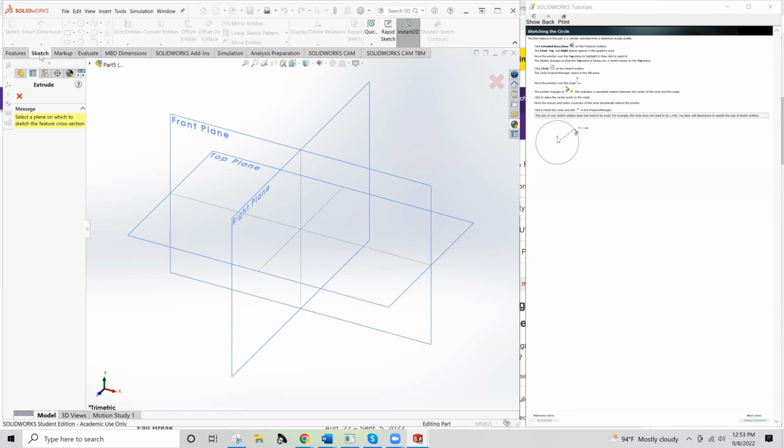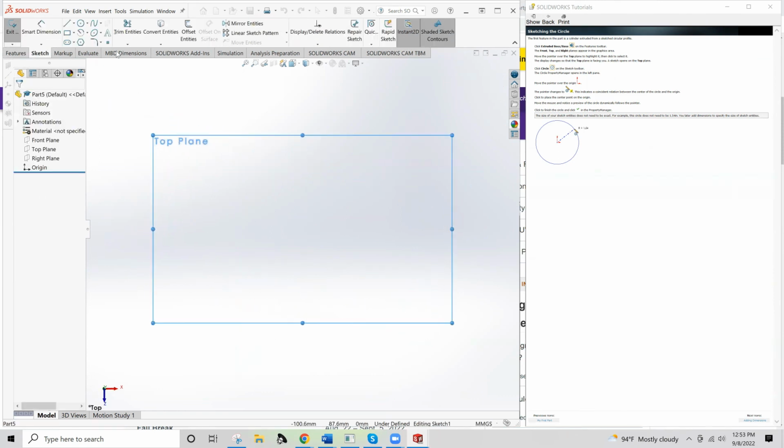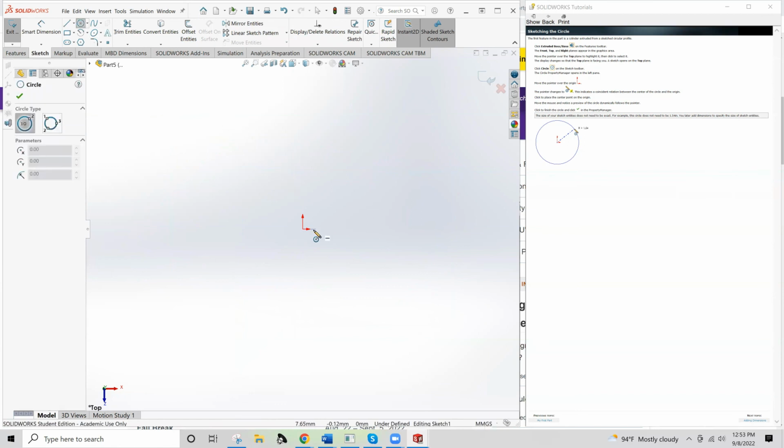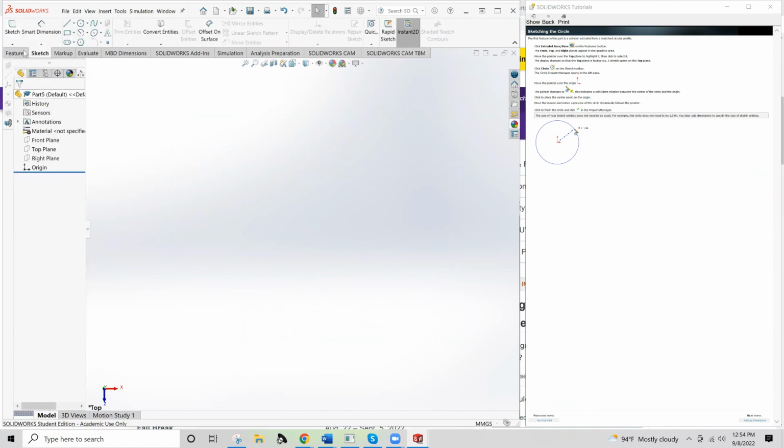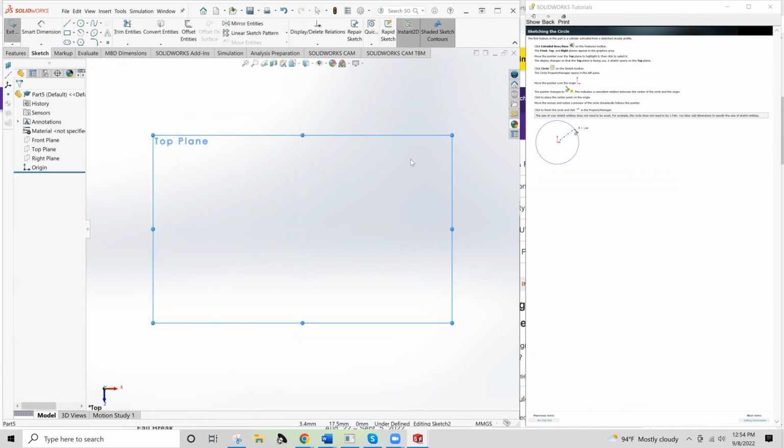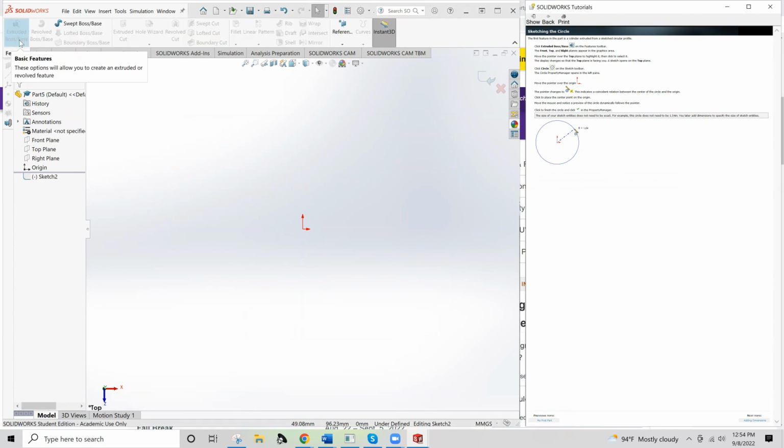They'll say, click on this extrude, and then hurry up and click a circle. That's a kind of backwards way of going about it. So I recommend just starting your sketch anyway, and then going through the operations, but it'll say, okay, where is this thing? It'll flip over to the basic feature and highlight it for you, which turns out to be really, really helpful.